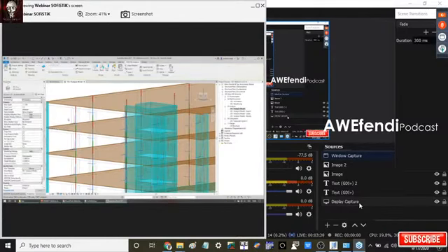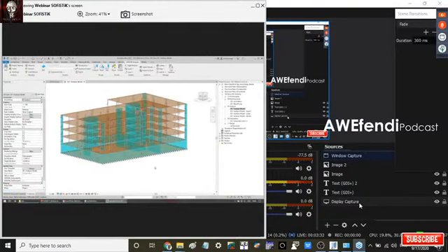So you will already have that in parallel, but in the general case, and this is our experience when working with customers, when you get a model from the architect, this analytical model provided by Revit automatically is usually not clean enough to conduct a proper analysis.